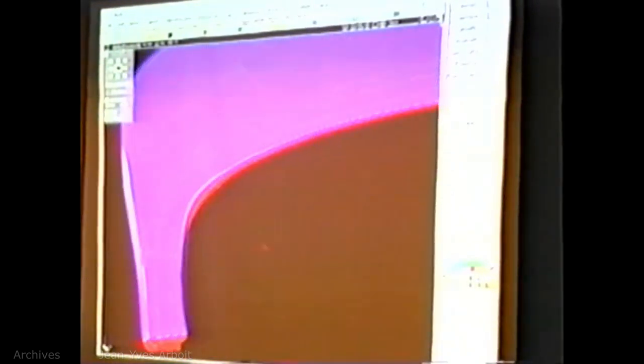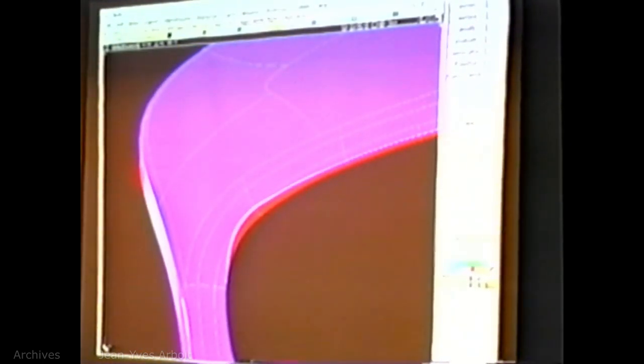And yeah, it's interactive too. So if I change the draft angle to 5 degrees, into the parting line with the curve on surface, it'll update. There's a difference right now. You know, we're using two tools, and that's something we're under discussion right now. We've got color analysis, and then we've got our draft tool, which I'll show you.